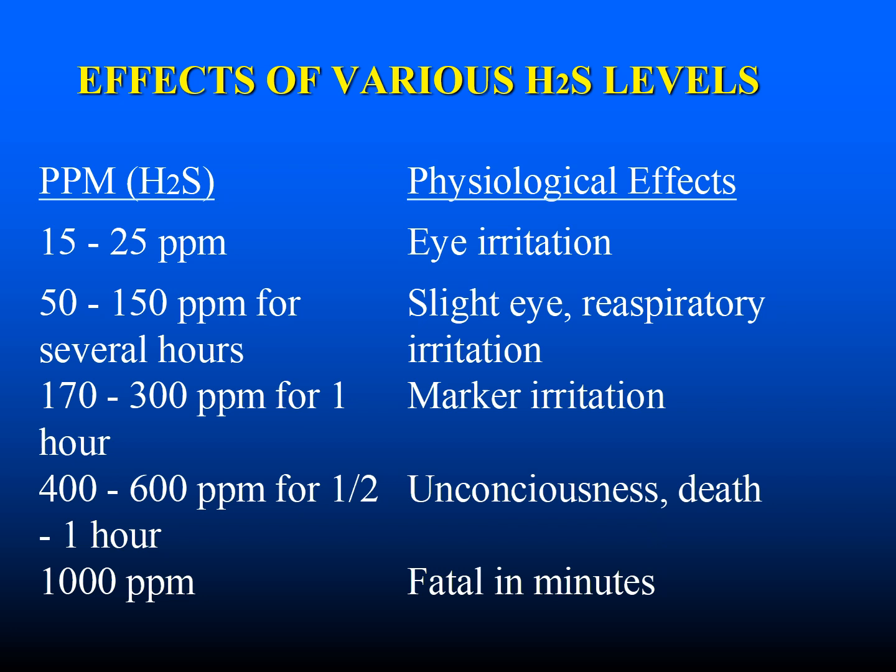At 170 to 300 parts per million for 1 hour, they'll have marked irritation. 400 to 600 parts per million for a half hour to 1 hour will cause unconsciousness and lead to death. And at 1,000 parts per million, it'll become fatal in minutes.